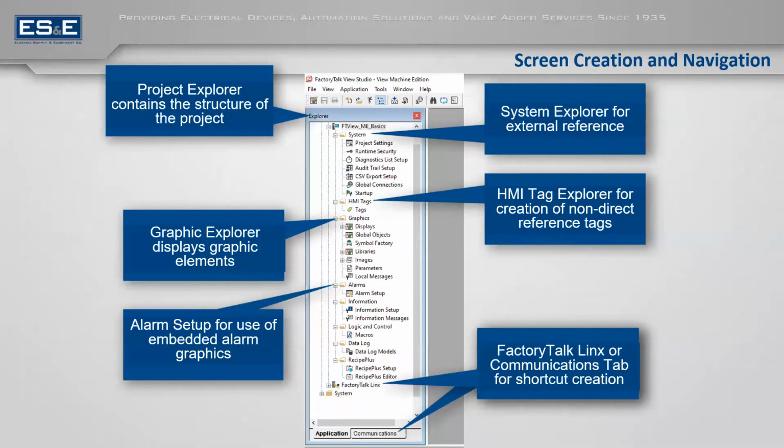So what I would do is I would recommend creating one alarm, browsing and getting it set up, then exporting your alarm event database there. Once you export your alarm, you could quickly modify it all in Excel by adding all your tags from an export that you can export out of the controller. Bring that and then re-import that back in. So that now you are attached to the extended tag properties to allow you to use that tag-based alarming.